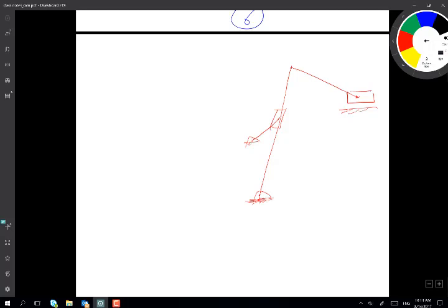All the fixed links, all of them are 1. We call them 1. That's all the stationary links. Like this end, that end, that end, all of them fall on link number 1, irrespective of whether they are attached on the drawing or not. It does not make any difference.